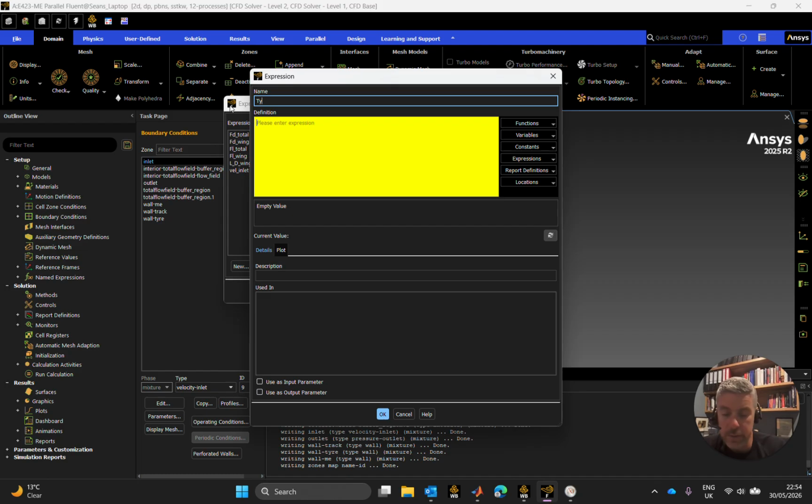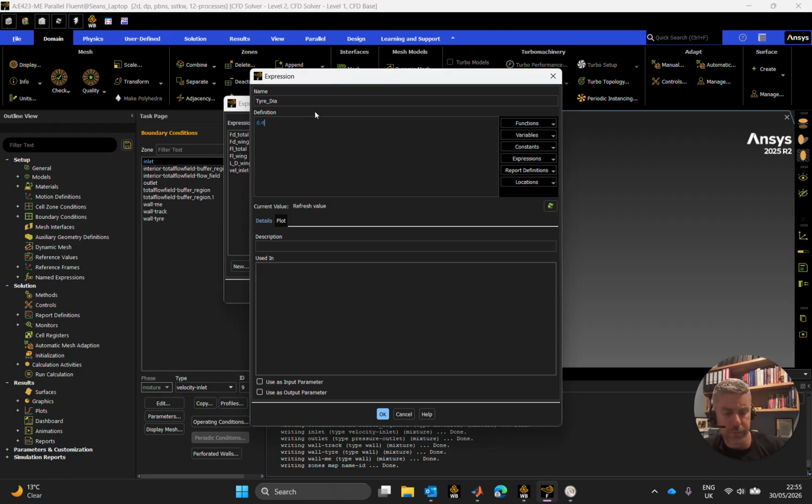So it's not even wheel diameter, it's tire diameter. Now the tire diameter, I'm going to put this in as a constant, and then I'm going to update it to be a formula. The tire diameter for that Hoosier tire, on a 10-inch wheel, was 414.02. So put it in meters maybe. Let me see. I put it in meters, 0.41402, and then let's specify that as meters. I'm going to use that as an input parameter.